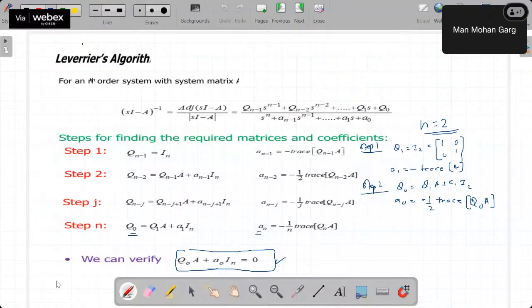Sir, will including parasitics or not including them in these equations give an appropriate result? Actually, if time permits, I will show you some slides in the afternoon session, where I have included these parasitics in this buck converter, and what is the difference between the results when we use the parasitics and when we do not use them in the transfer functions. Also, we have to see the state variable behavior in that mode. If it is impacting, then we cannot neglect.